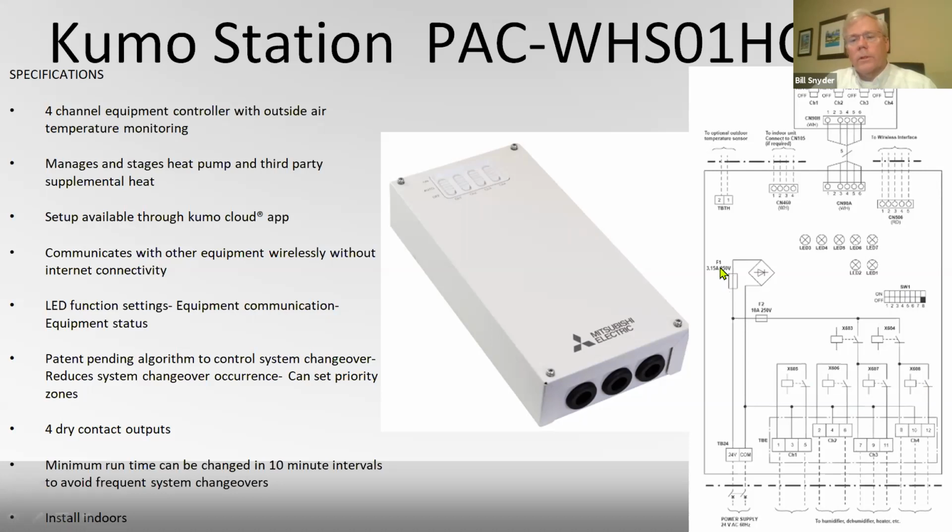You can say, for instance, through the Kumo Cloud app, that if the temperature is below 0 degrees, then I want to allow my boiler to come on, or I want to allow my humidifier to come on. If you sell the Kumo Cloud with the little humidity sensor, you can control the humidity with one of these relays. Maybe turn your condensing unit off with one and turn a boiler on with one. Just a kind of unique thing that you can use.